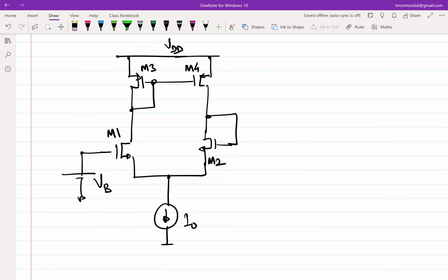Okay. The other way of arguing, which will help make another point, is this: 0 and a completely one-sided shift is probably an extreme condition. Let's assume that slightly higher current is flowing through M1 than M2. You can go either way, but let's assume that. If that is the case, if more current is flowing through M1 than M2, then what is happening?